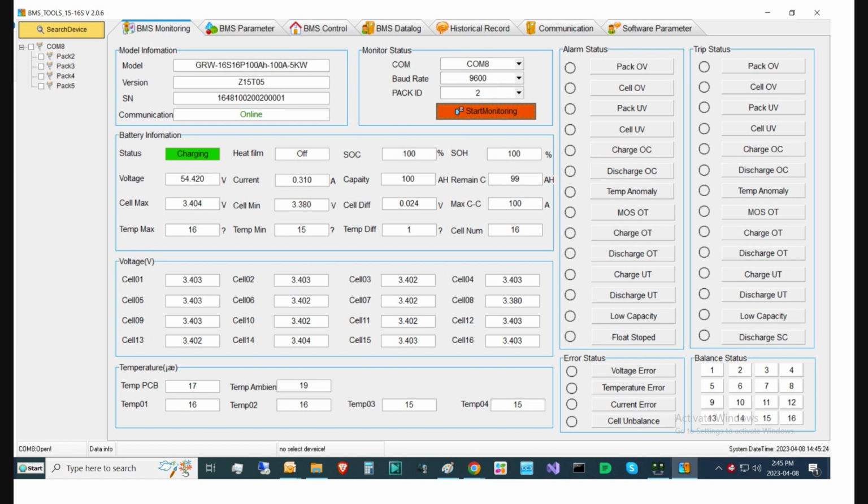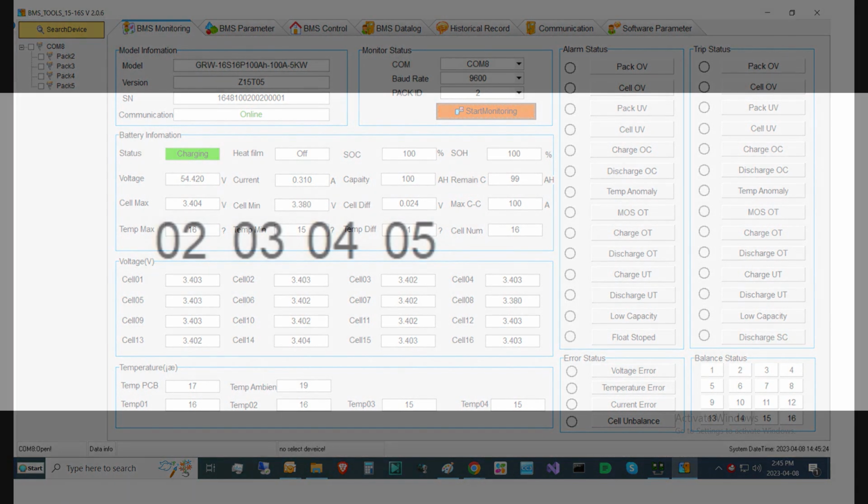And that's when I noticed that the BMS software sends out a 16-byte string of data to each of the batteries, and each of the strings is addressed to a respective battery. In my case, I have 4 of the EG4LL batteries, and they are addressed 02, 03, 04, and 05. But I only use battery 02 for this test.